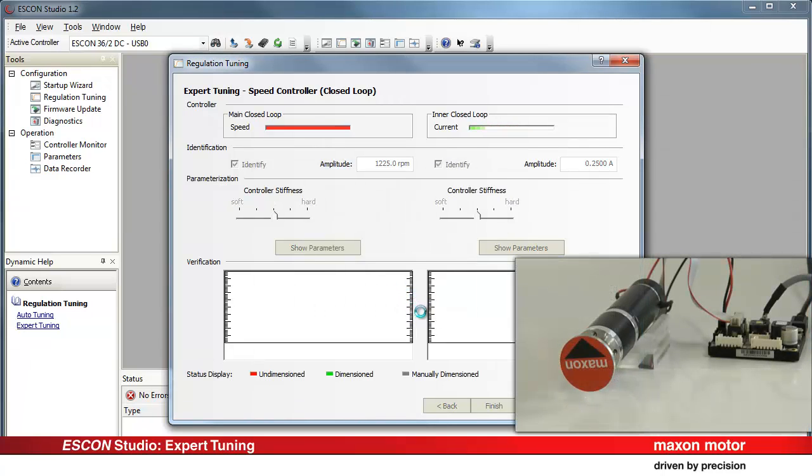The tuning runs fully automatically in 3 steps. First, the tuning tries to find out the relevant parameters of the plant. This is called identification. The system reaction to left-right excitation with different frequencies and amplitudes is monitored.